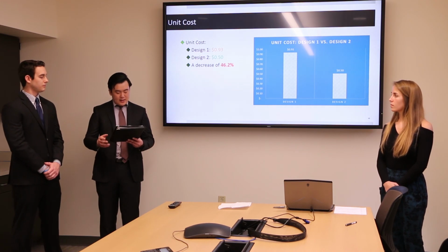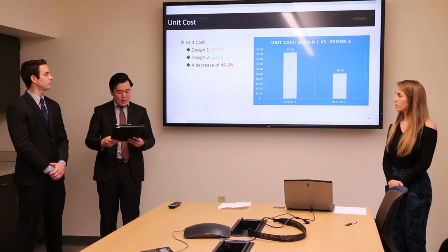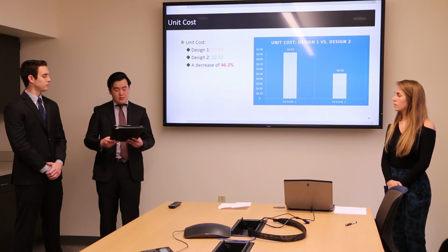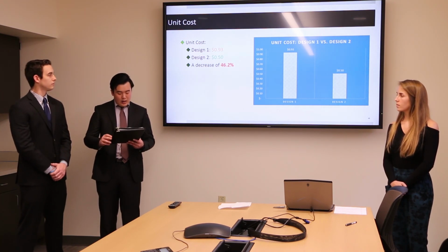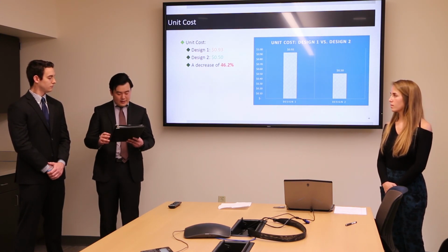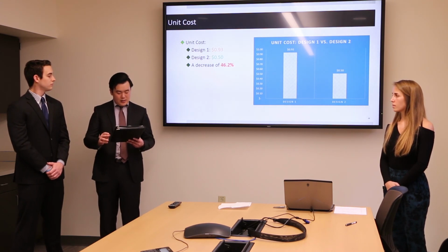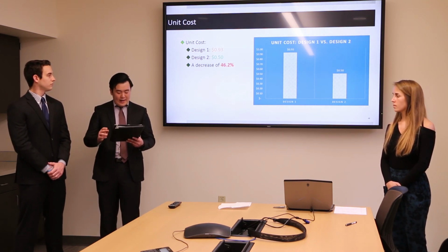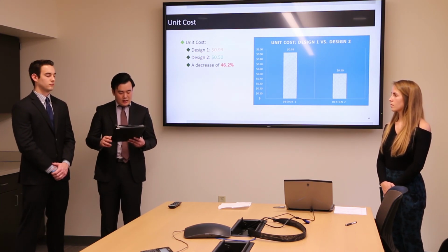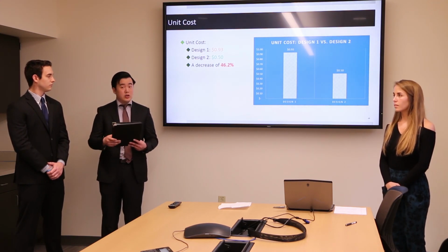Secondly, the project is based on some idealized and impractical assumptions due to the lack of real-life experience about the actual injection molding industry. The unit cost is a theoretical minimized cost for our design too. However, from this project, the most important conclusion we made is that for a massive production scenario, like in this case, the most expensive process will be the actual value-adding processes in common industry. By saving cost of each unit's value-adding process, even at the risk of increasing the non-value-adding process cost, the overall cost will be reduced significantly.